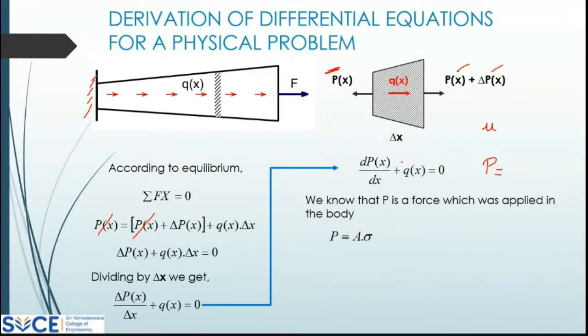So P is equal to A into stress. Stress is equal to force by area, so in that case, P is area into stress. Now, stress I can write in terms of strain, E into strain. Okay, you know that stress is equal to Young's modulus into strain, so stress by strain is Young's modulus. I am applying that here.